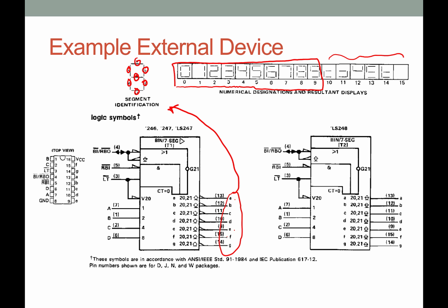But then what you'll have to use as your outputs from your board now will be going to these capital A, B, C, D ports. And you can see also here's VCC and ground. But you'll be wiring the ABCD, and you can see that if you output a decimal 0 as you count through this hex, basically 4-bit number, you can count through 0 through 15 to display these different digits.